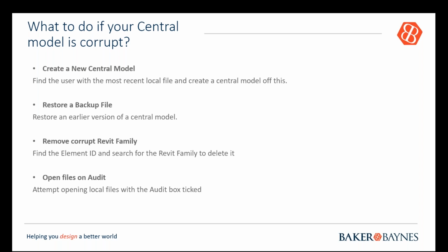But if you're unable to do that, you maybe want to restore a backup file. I'll show you where those buttons are. So you want to restore an earlier version of the central model, and that's going to take probably the last synced option, or whatever the case is.